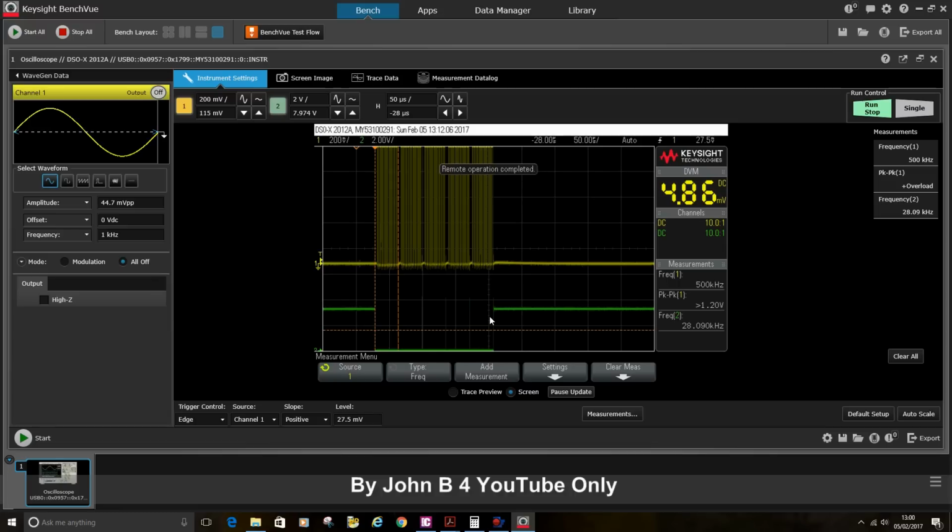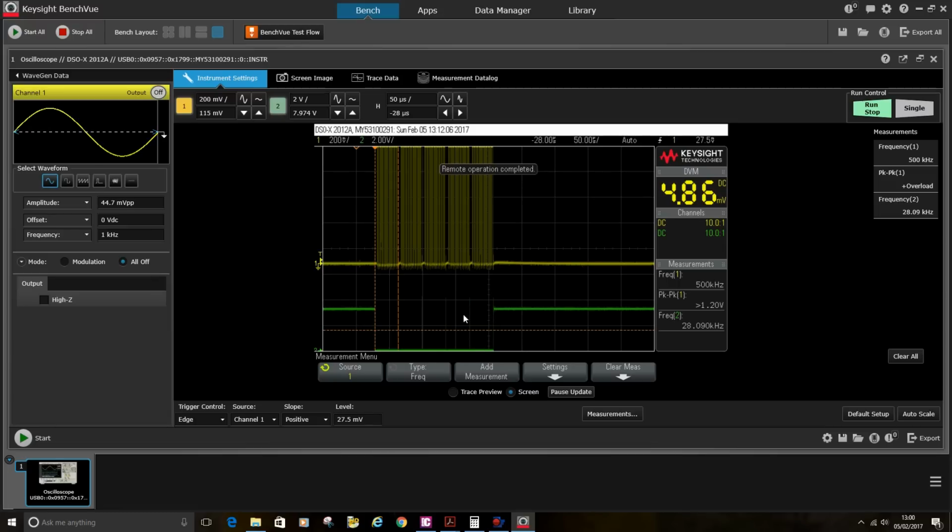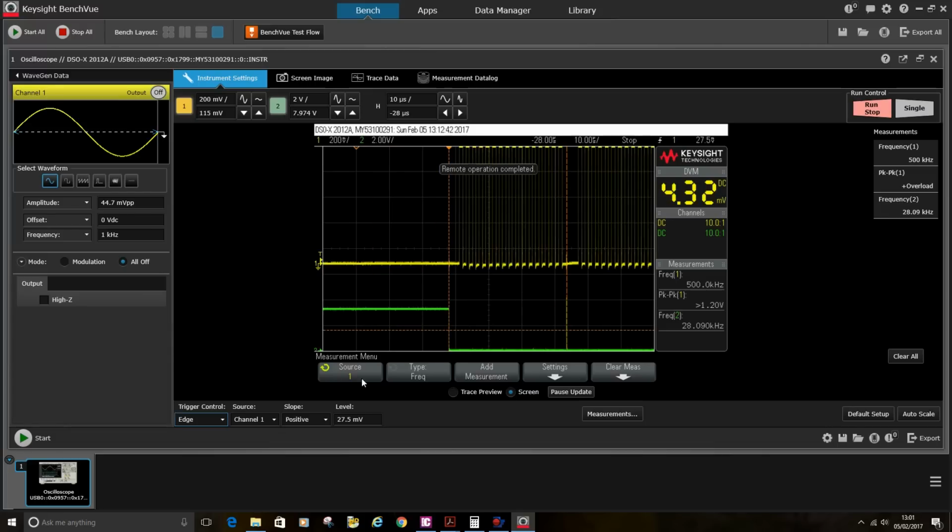Anyway, this is the system. This is my SPI clock. I've just decided to shift. I have to wait for this screen to update. There's my 5 writes, and this is my chip select, this green line. I'll wait for it to synchronize again. You can just see tiny little spikes there. So what I'll do, I'll synchronize it on this and expand the view.